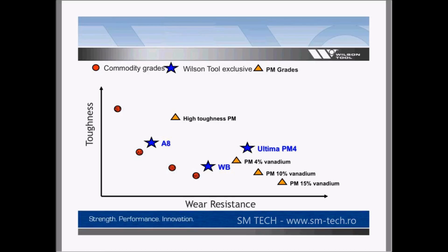But as you get further along, each one, like I said, a couple points in Rockwell is 20% gains in wear resistance. As you move further and further on this chart, that wear resistance gets pretty strong, and you're not giving up a lot. So keep that in mind when you balance that out. Look at the cost and just determine really what helps you out in the end.